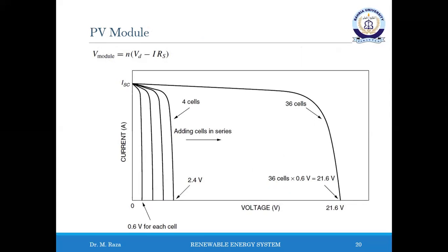Instead, the basic building block for PV applications is a module consisting of a number of pre-wired cells in series, all encased in a tough weather resistant package. A typical module has 36 cells in series and is often designated as a 12-volt module even though it is capable of delivering much higher voltage than that. Some 12-volt modules have only 33 cells, which can be desirable in certain very simple battery charging systems.